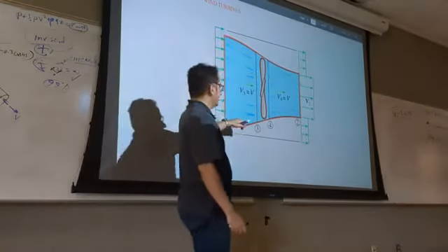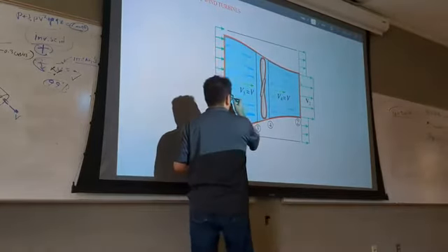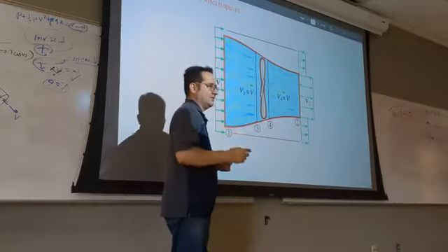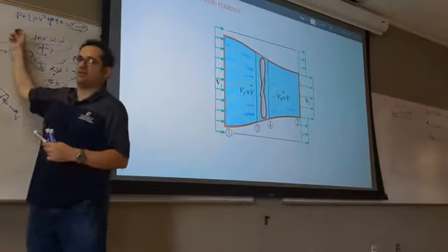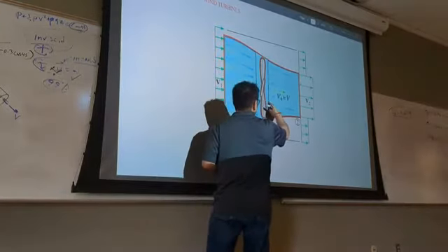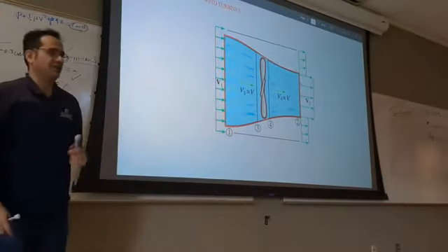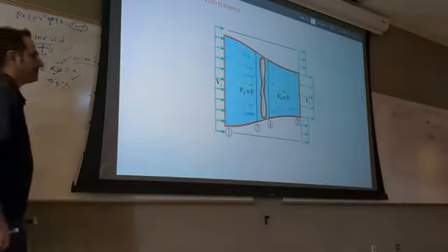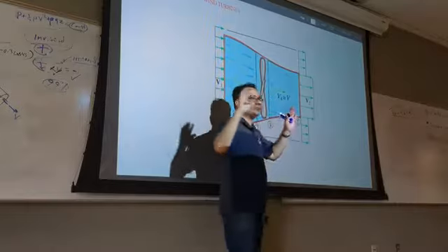Why are we making 3 control volumes for that? Well, look, can I write the Bernoulli equation between these 2 points? No. When I say Bernoulli, I'm talking about the inviscid Bernoulli assumption. Yes, there is a streamline going here and then going up, and you may say I can write Bernoulli, but look, what was the assumption? Everywhere should be inviscid. What happens in real life when the fluid comes just near that? You have viscosity.